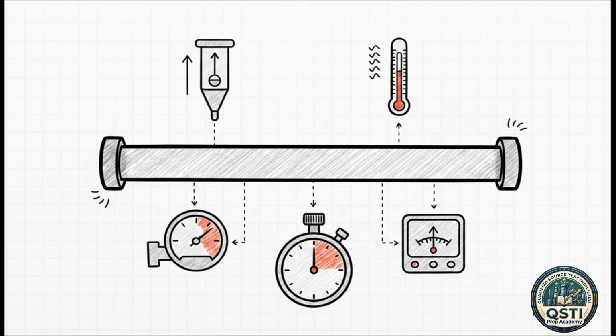On top of that, it needs a temperature gauge accurate to within plus or minus 2% of the minimum absolute stack temperature, and a pressure gauge accurate to within plus or minus 5 millimeters of mercury. You're also going to need a barometer that's calibrated against a mercury or NIST traceable barometer, and a simple stopwatch that measures to within 1 single second.